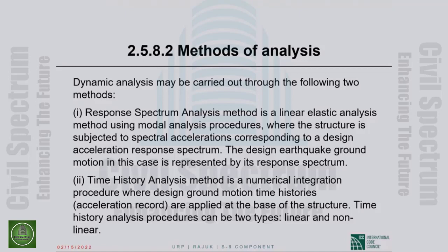These shapes are the shapes of the different modes of vibration, as we call them. They are like single degree of freedom systems, as we will describe. I don't want to go into terms now. Anyway, we analyze the different modes like single degree of freedom systems, and then combine the responses of the various modes to come up with the response of the structure. I know what I did is not the best, but it will become clearer as I take you through the procedure itself.